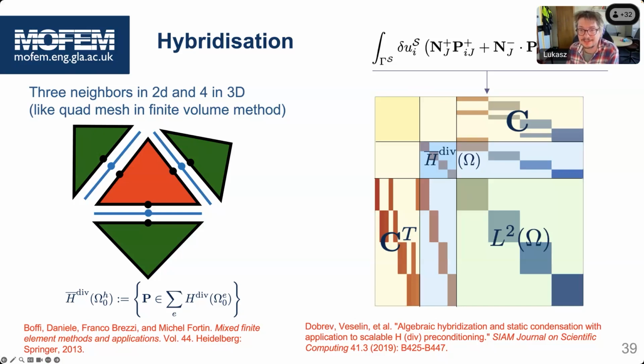So then we get a system like that, when on the skeleton you introduce the Lagrange multiplier, which is in L2 and has the interpretation of the displacements. And then this Lagrange multiplier connects everything together, enforcing the continuity which was broken. At first instance it makes no sense, but in fact this is the solution for all the problems.